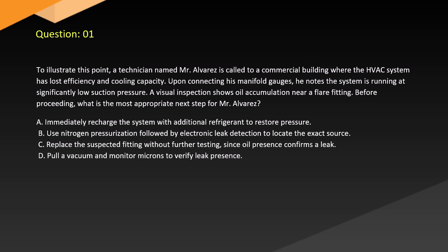Question 1. To illustrate this point, a technician named Mr. Alvarez is called to a commercial building where the HVAC system has lost efficiency and cooling capacity. Upon connecting his manifold gauges, he notes the system is running at significantly low suction pressure. A visual inspection shows oil accumulation near a flare fitting.